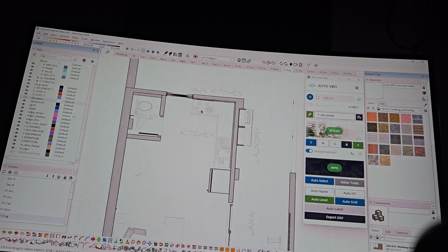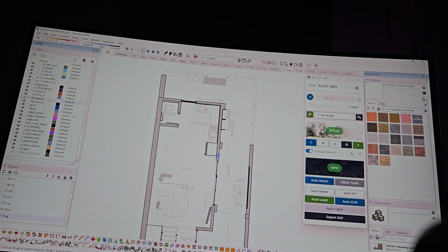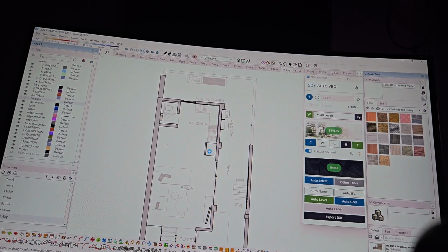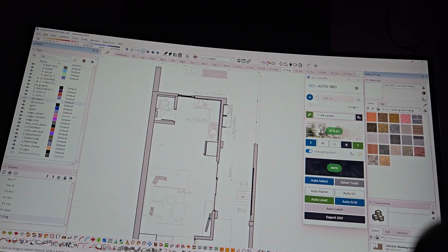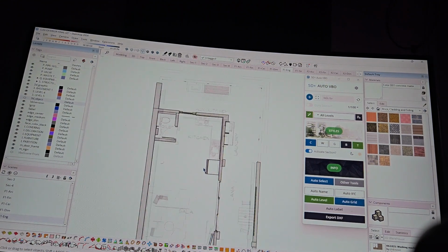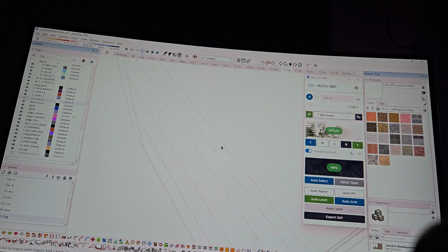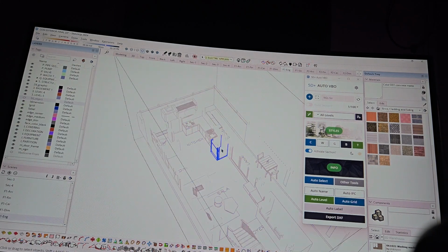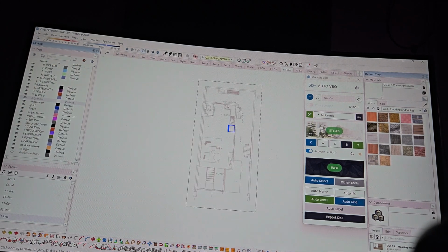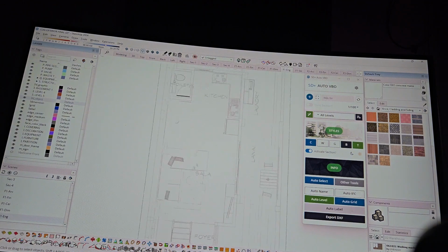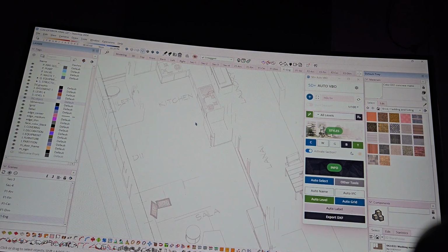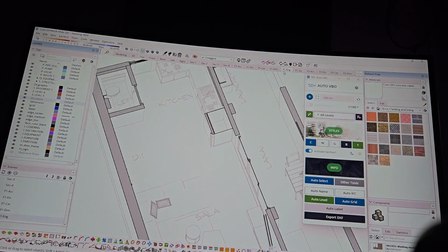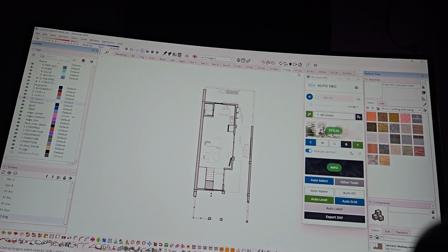And then I also turn off things that get sectioned that are not part of the walls, like equipment, refrigerator, TV, stuff like that. So it might get confusing, that's why I can just hide it by pressing letter H, something like that. Or I could use the 2D version of this and place it below and put it under the 2D tag.